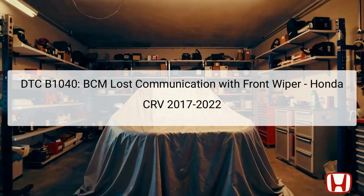The following presentation outlines the troubleshooting for DTC B1040, indicating that the body control module, BCM, has lost communication with the front wiper. This error typically occurs when there is a disruption in the wiring, a failure in the BCM, or issues with the windshield wiper control unit or motor.